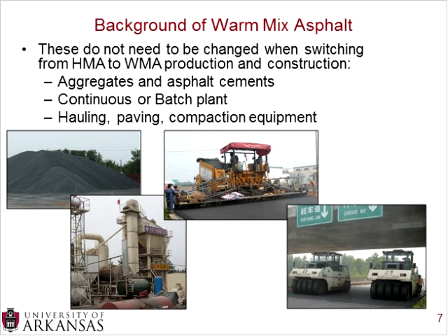Now when thinking about warm mix asphalt, these things do not need to be changed when switching from hot mix asphalt to warm mix asphalt production and construction. You can use the same aggregates and asphalt cements. You can use either a continuous or a batch plant. Now if you do use a technology that requires a slight change in your plant, you will need to do that.